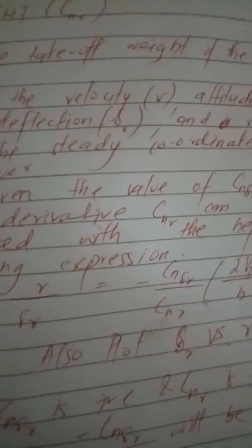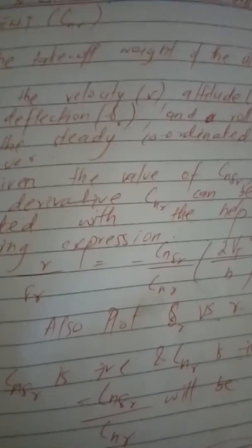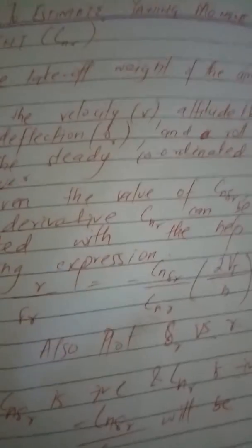So, flight test to estimate yawing moment. Okay, we need to actually test this equation. All the assumptions, which are mostly 0: beta is 0, r is 0, p is 0. We have to consider how we are going to relate our assumptions to a flight test, and what are the possible steps that we may come across, so that we can say what the assumptions are that we took first initially, which stand during the whole flight test, from the beginning till the landing phase.